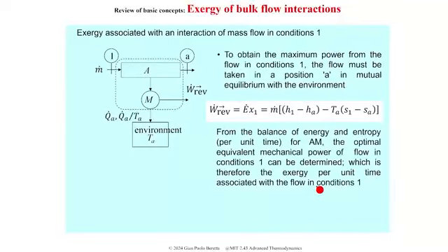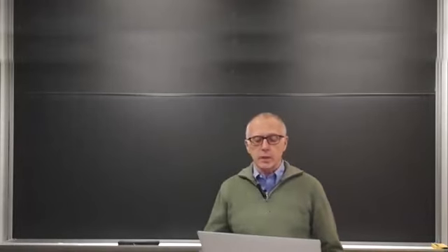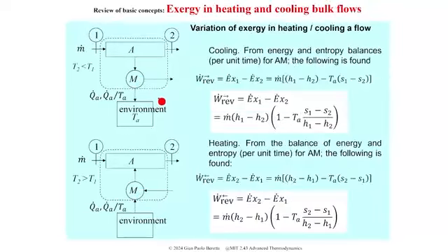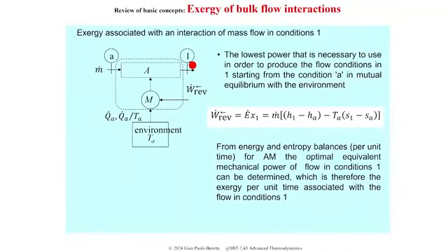Anyway, okay, so we are talking about exergies, and today we'll hopefully finish this part. Remember last time we talked about the exergy associated with a bulk flow state, which is this linear combination of enthalpy and entropy, and which represents the maximum work you can extract from that bulk flow state in this situation, but it also represents the minimum work to produce that same bulk flow state from environmental conditions.